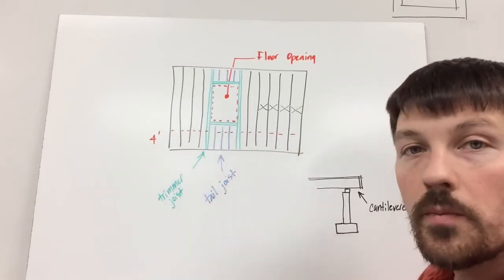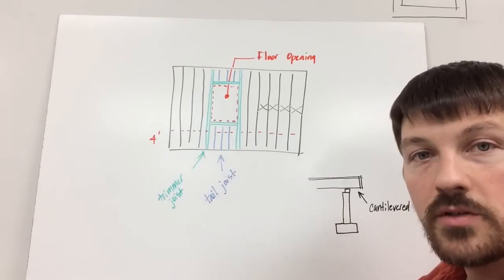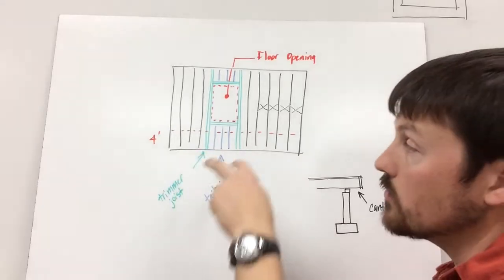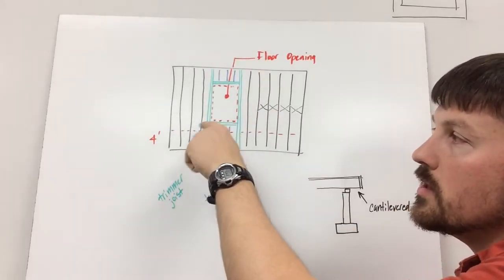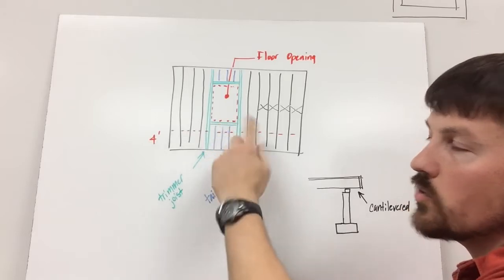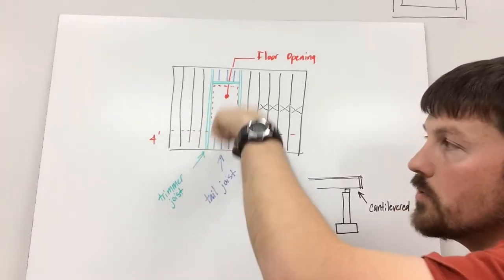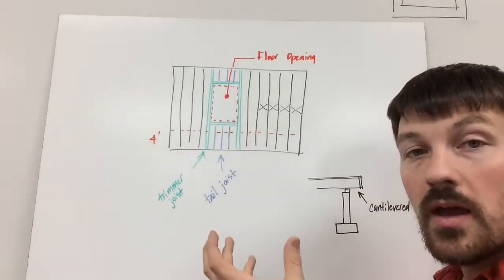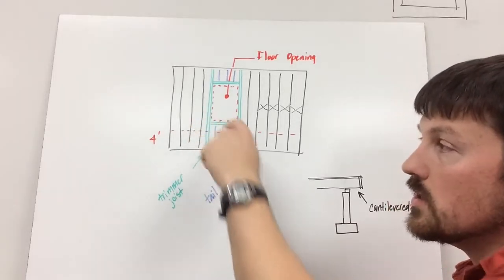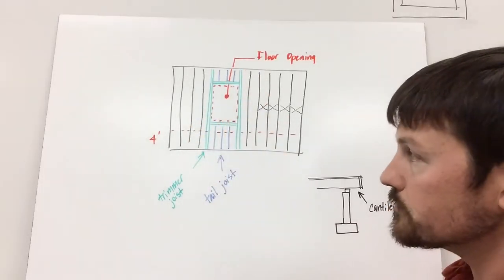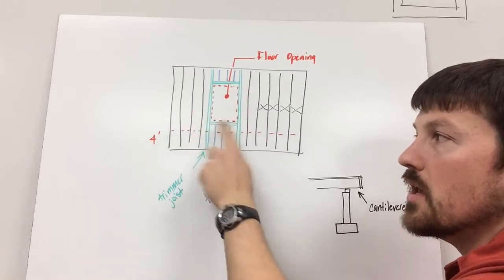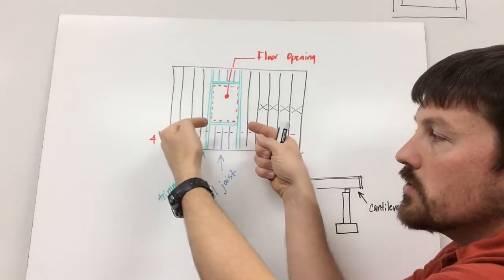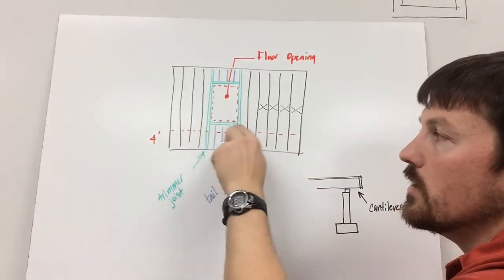And when you're going to build a floor opening, there's kind of a set procedure that you would go through. You would put in the inside trimmer joist first, and you'd run them through. Then you would put this horizontal joist here. You could maybe call it a header joist, and I would put the furthest outside, the closest to the tail joist, so that when you're putting up the tail joist, you can just nail right through that header joist into the tail joist, and do that on both ends. Then you would double up this header joist, and that way you still have access to nail in from both sides through that trimmer joist into this header joist.